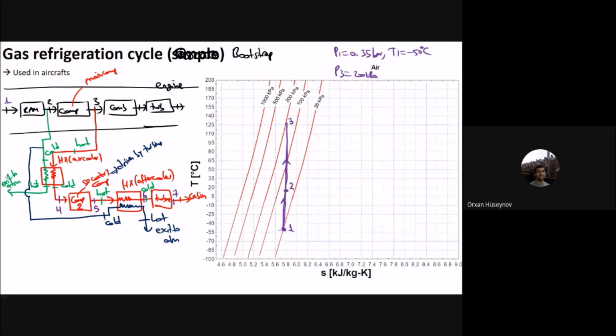And then I will have that drop in temperature to 4. I don't know how much the temperature will drop. This actually depends on the application. So you can see that this is very similar to intercooling. They are cooling the compressor between these two stages. So you will have 4 here. Then from 4 you will have 5. So you have 1 to 2, which is RAM, 2 to 3 is compressor 1, and 4 to 5 is compressor 2.